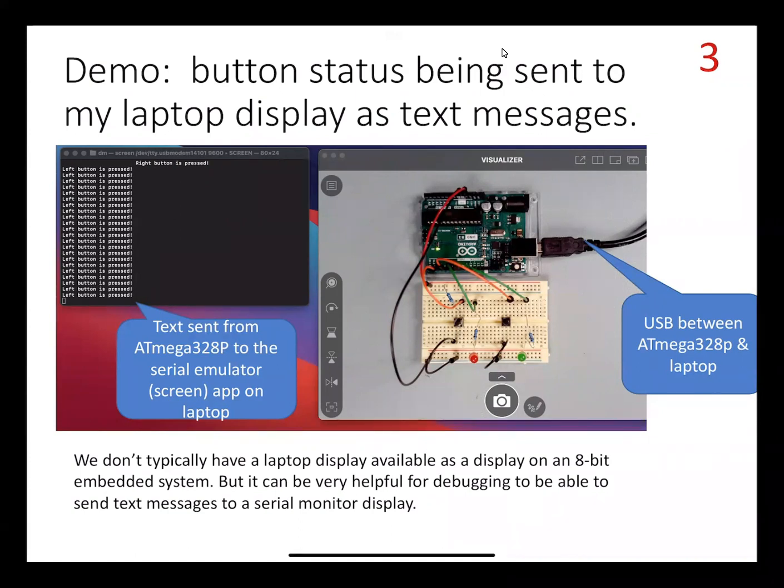And it can be complicated because you can have problems on the software side, you can have problems on the hardware side, you can have problems on the hardware software interface. I mean, if you change the code and then you reflash it, did it successfully flash? Did the new code ultimately get transferred to the ROM on board the microcontroller? These are some of the things you don't know when you're trying to debug. So what I want to show you right here